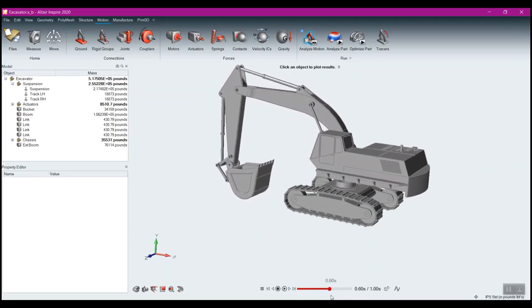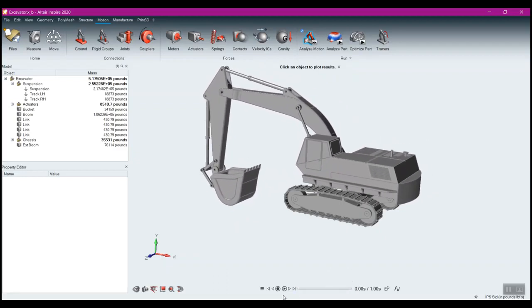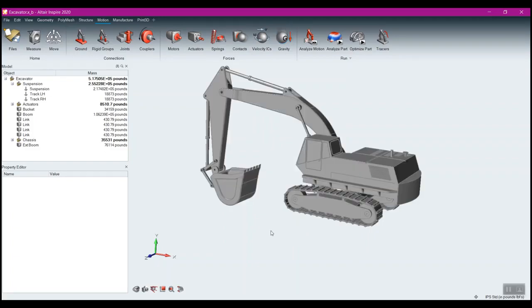But this also has revealed another problem to me: in this case, gravity is going in the wrong direction. So we'll break from going across, and we'll pop here to gravity. And we'll select that. It looks like we want it in the y-axis, and it defaults to the negative, and that is the standard gravitational acceleration. So now if I quickly run it again, it's exactly what I was expecting. So that takes care of our ground, and it takes care of gravity.